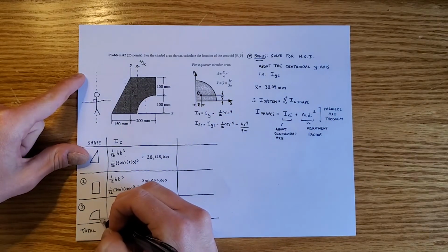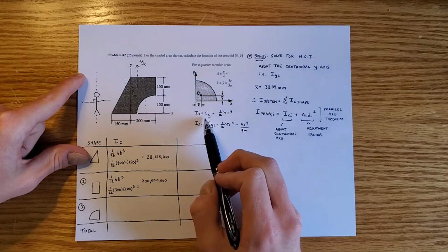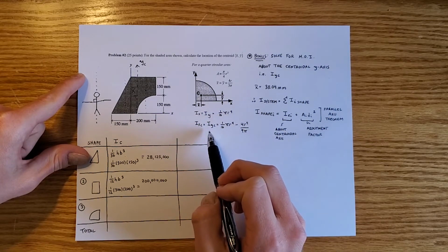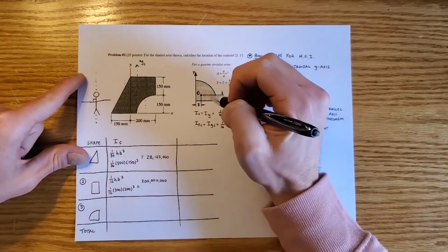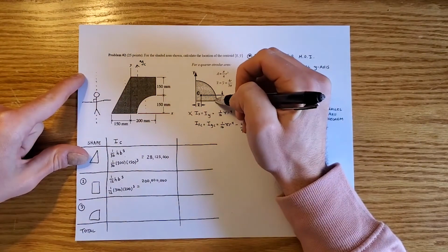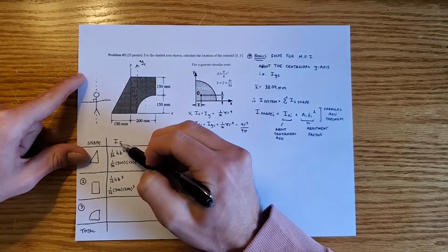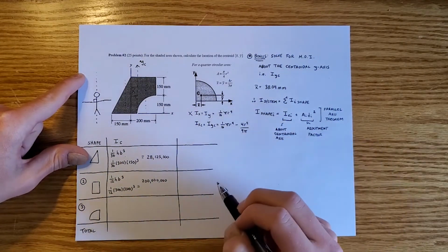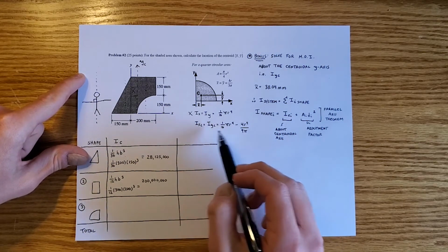Now what we have to do is our quarter circle. Now this isn't found in your table, but we can see up here we've got two options. We've got Ix and Iy is 1/16 pi r to the fourth, or we've got Ixc and Iyc equals this funky looking thing right here. Well, I can tell you right now that you almost never need these on the exam. The reason is because that's telling you the moment of inertia from this axis. But we don't care about that axis. We want the I-centroidal for each shape. That's exactly what we have in our parallel axis theorem equation. So what we want is this. And we can see that these are both the same.